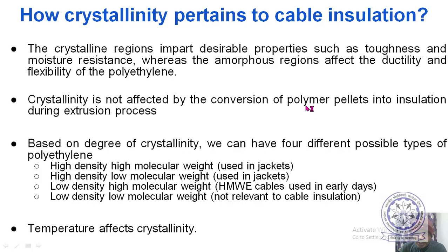And this will be fed into the extruder. The extruder will put the material on the central conductor in a process known as extrusion process, by which a cable is made. So, whatever crystallinity is there within the pellets, the same amount of crystallinity will be there after extrusion process also. So, this sentence says that crystallinity is not affected by the conversion from pellets to cable.